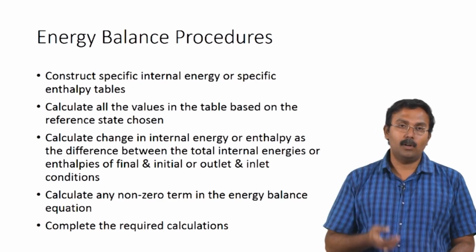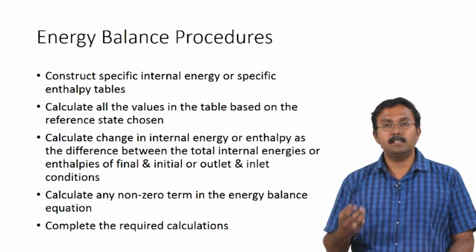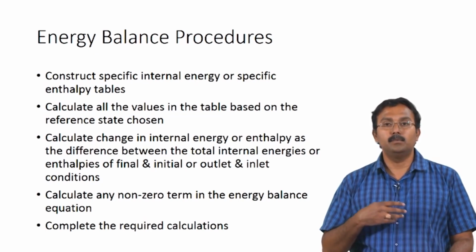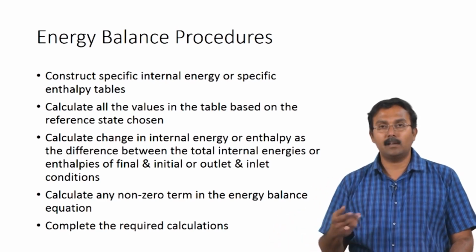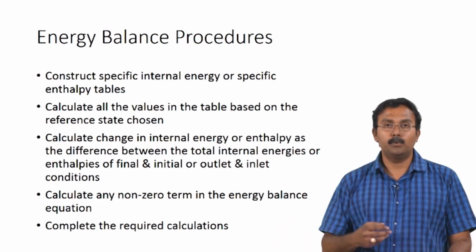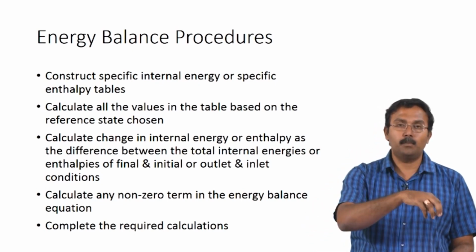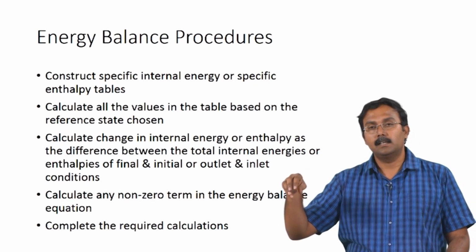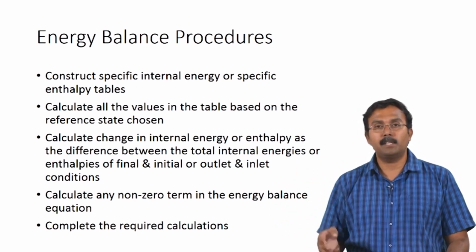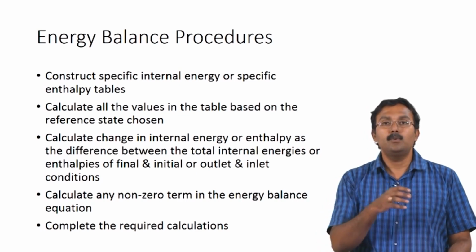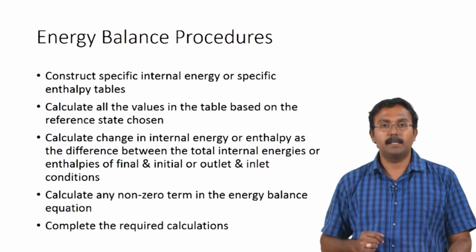So, which would include all the flow rates or masses or moles, and also the internal energies or enthalpies using the reference state as the point of reference. You would have to calculate these values. So, what you would have is the reference state as the first point, and it reaches the condition, whether it is the inlet condition or the outlet condition. So, you can build hypothetical paths which are required to calculate this value for internal energy or enthalpy.